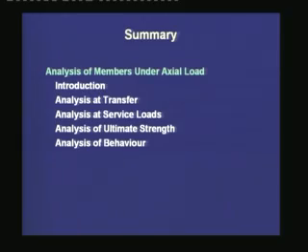Next, we moved on to the analysis of behavior, where we studied the complete load versus deformation curve of an axially loaded member, and we have seen that this needs three principles of mechanics. The first is the equilibrium of forces, which means that the external load is equal to the internal forces generated in the concrete, in the reinforcement steel and the prestressing tendon.